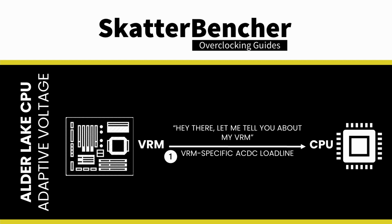In step 1, the motherboard's BIOS tells the processor the current load line characteristics via AC-DC load line values. The AC-DC load line characteristics are a way for the motherboard to inform the CPU about its specific VRM design. This is highly important in situations where the CPU goes from idle to load and there's a voltage droop.